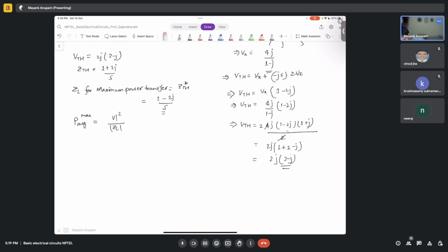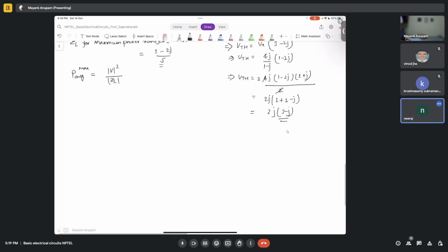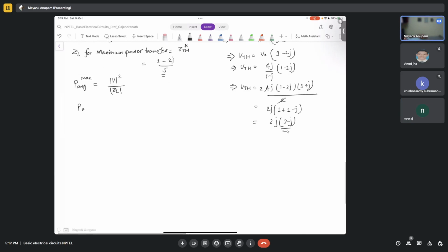And that too, maximum power is how much? 4, right? Okay sir. How much is that? 4 or 2? Tell me. Come on, fast. Sir, I don't remember that. I think I have to look up in the books. Okay, so let's derive it. So what is P average? P average is how much? Mod of V square upon 2ZL, right?